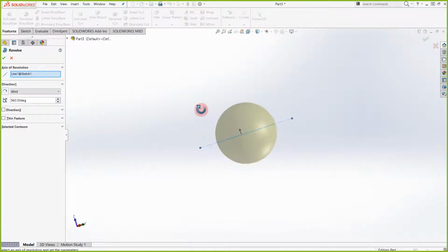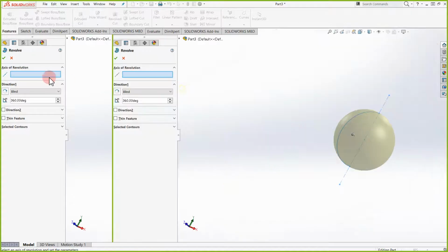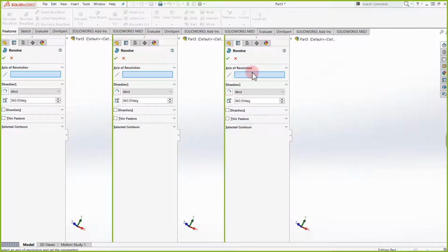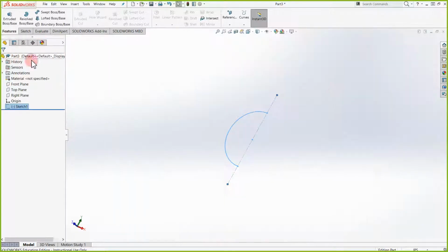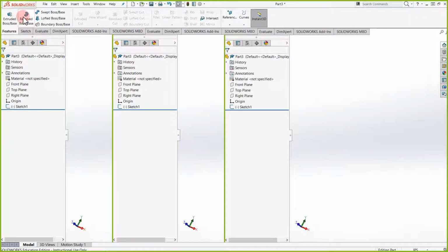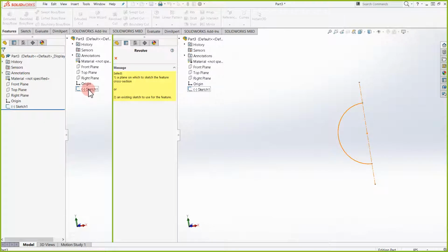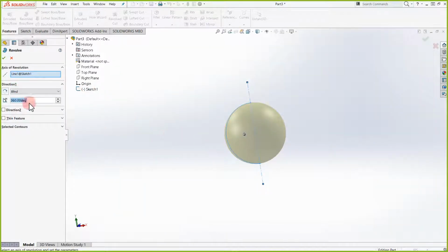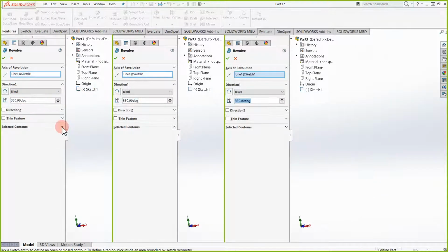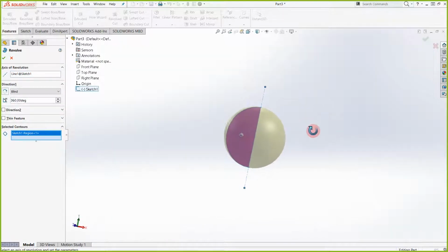So as you can see here, all I did so far is I clicked and it worked. But let's say it didn't work right away. What you would need to do, let me just close this again. My computer's going. Let me go back, not click on the sketch this time, and let's do revolve. So now it's asking us to choose our sketch. We go here, click on our sketch, and now we have our piece selecting. The one we wanted. If I click here, it's going to take that sketch and revolve it around.